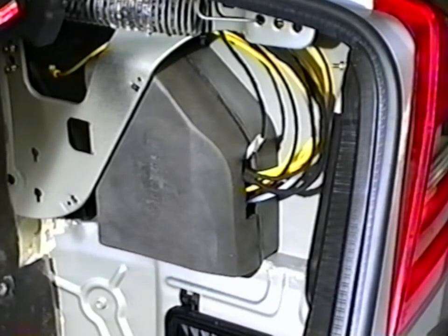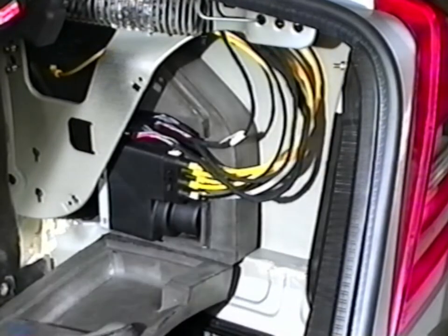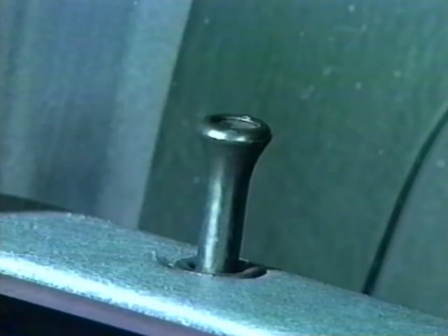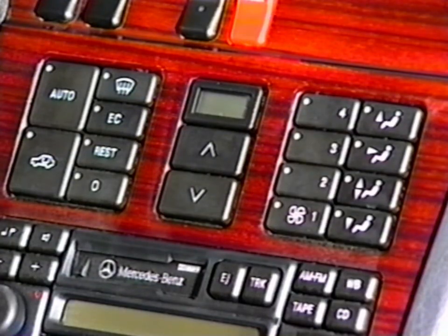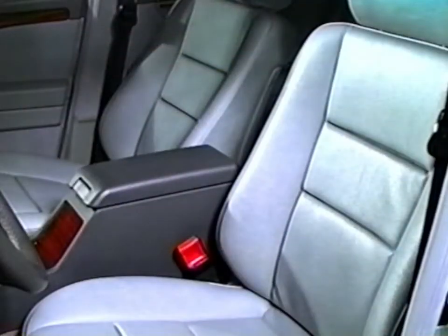The pneumatic system control module and pump assembly is located in the trunk. There are 2 different version pumps available: the standard version and a version for vehicles with multi-contour backrest. The system provides pressure and vacuum to operate the central locking, vacuum assist for the intake manifold dependent climate control system, and pressure to operate the multi-contour backrest.